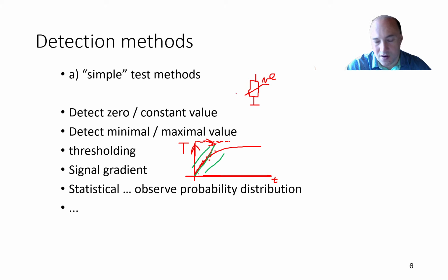Here we have our temperature sensor, here we have some fixed resistor, and this will be plus some voltage, let's say, for example, plus 5 volts, and the output signal is here, and this goes to your microprocessor with an AD converter. So we can see that the voltage that we measure here will be a function of this temperature.